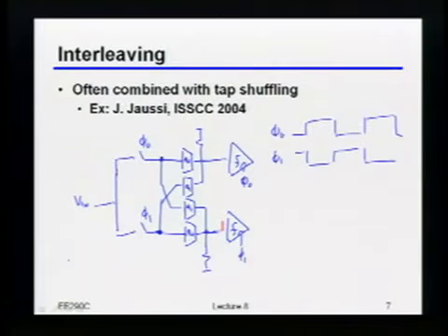As we'll talk about a bit more later on, it does depend a bit upon what you're doing afterwards. If I'm really just making decisions, then it probably makes sense to do this, because all of the latency and bandwidth of everything after the sampling point is relaxed by about a factor of 2. Whereas if I reserialize it, I have to deal with the full bandwidth again. But if I'm trying to build a DFE after this, it's not so clear that having the relaxed bandwidth helps, because as we'll talk about in a second, the DFE itself will introduce a bandwidth constraint.